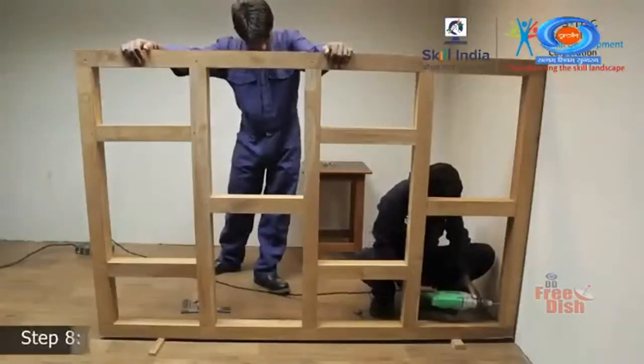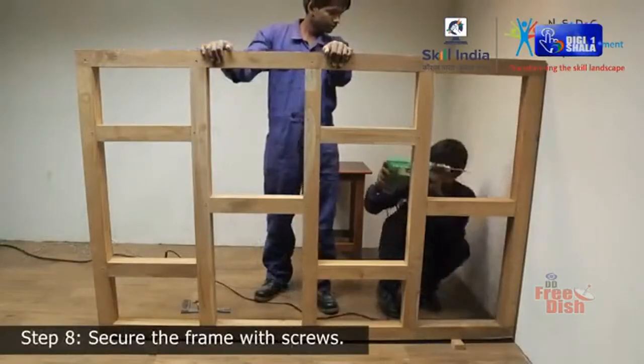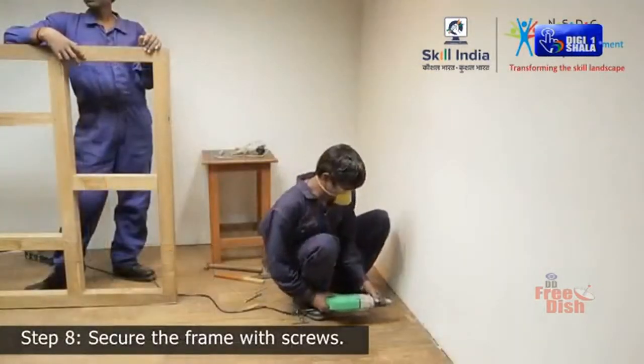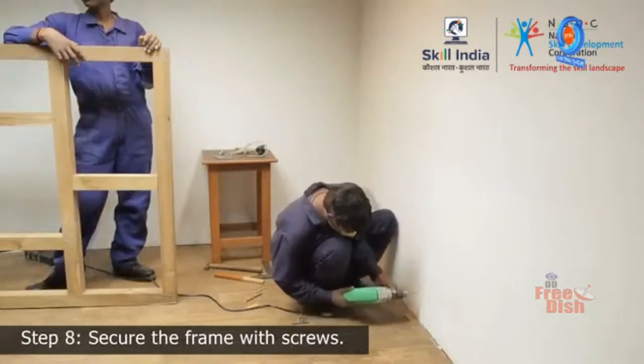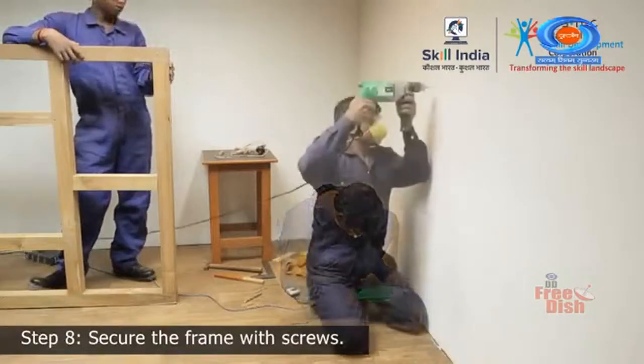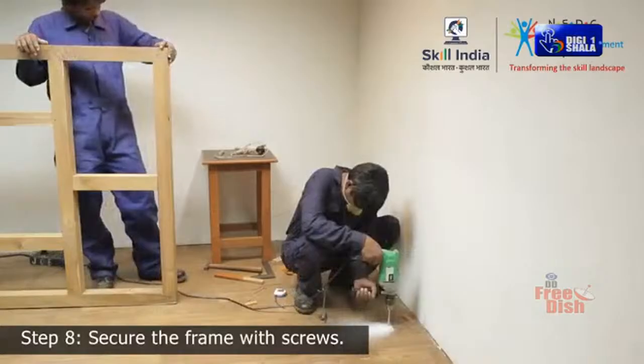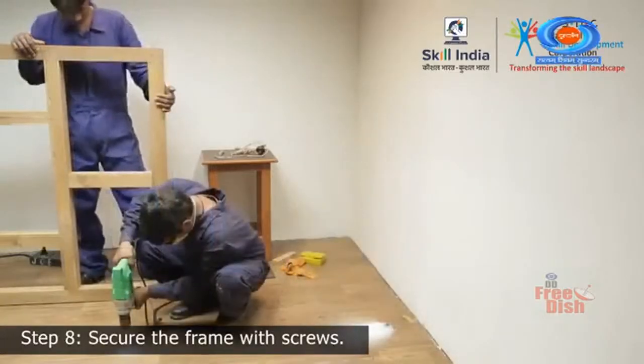Step 8. Secure the frame with screws. Once the frame is aligned, drill a hole on the frame and the wall and put the screws in place and tighten them to secure it. Then secure the bottom to the concrete floor in the same manner.